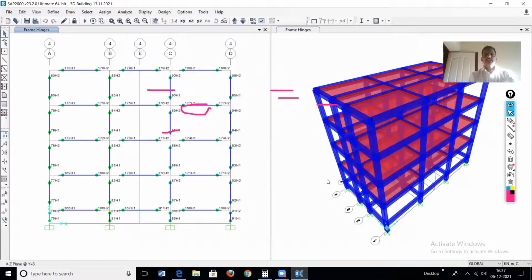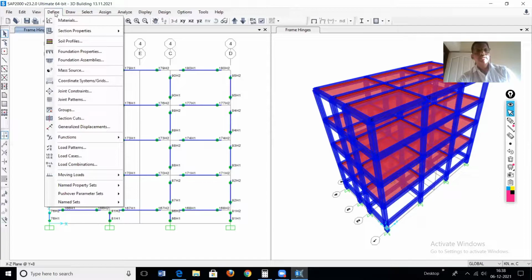Now these are all the hinges we are seeing for the columns. In this way we have to assign the material nonlinearity. Which option have we adopted? We have chosen the lumped plasticity approach. So in SAP2000, this is the option of assigning the material nonlinearity using auto hinges. Then, just before we go for the time history function, I will show the dead load nonlinear case.